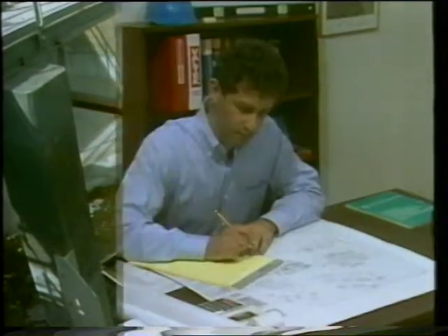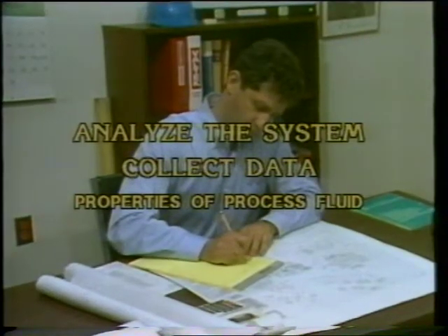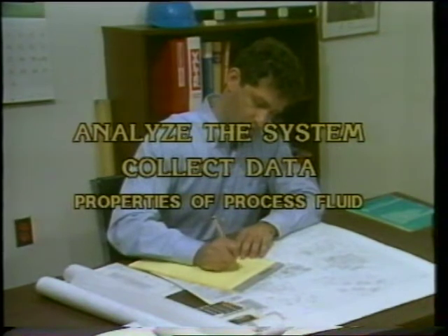If the fluid is a slurry, it's also necessary to determine the weight percent and volume percent of the solids. You'll also want to know the size of the largest particles, as well as their hardness. Clearly, these factors influence valve sizing and selection. Properties of the process fluid aren't the only concern when selecting a valve.